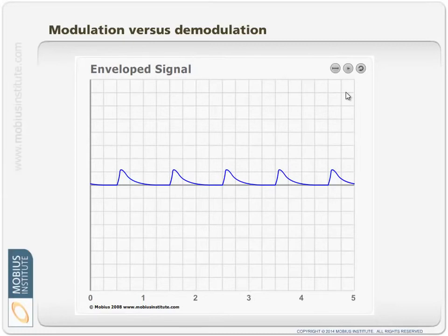So it's a very effective technique, but as you can see, we use demodulation in the case of outer race faults on bearings where there was no modulation in the first place. It's a coincidence that we've got modulation in the case of inner race faults, and we use demodulation to analyze it. They're just two different processes altogether. But what I would tell you is that we can use that process even for gear faults and the broken rotor bars as well. Again, nothing to do with the fact that they actually cause modulation.